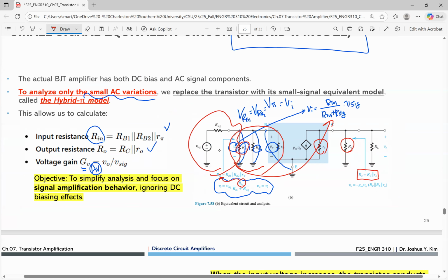Okay. So V sub 0 is Ohm's law, IR. So what is I here? This is the current source. Do you remember in the saturation mode, the MOSFET, I'm sorry, the BJT works as a current source. So in here, I is G sub m times V sub pi, and the R is what? R sub 0, R sub L, and R sub C. Okay, and could you see the current source direction like this one?